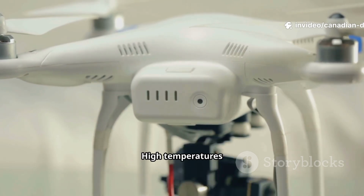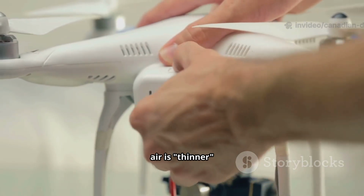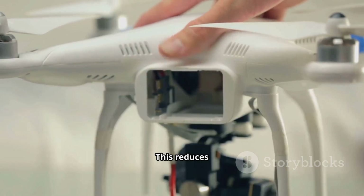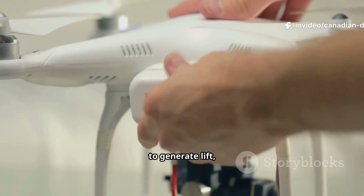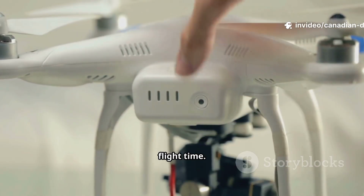Density altitude. High temperatures and/or high altitudes mean the air is thinner, less dense. This reduces propeller efficiency, meaning the motors have to work harder to generate lift, which also reduces flight time.